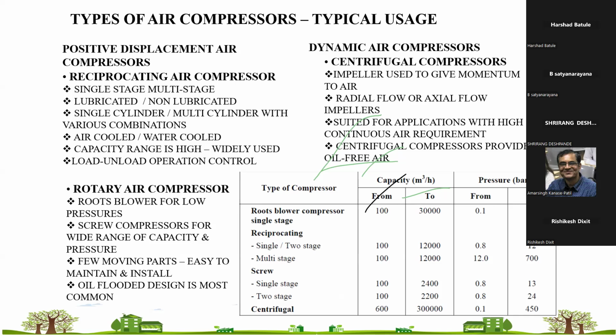We will go for an air cooled screw compressor. That's why screw compressors are more frequently used. And then there is efficiency, or specific energy consumption: screw compressors are more efficient, and all these things are coined nowadays.